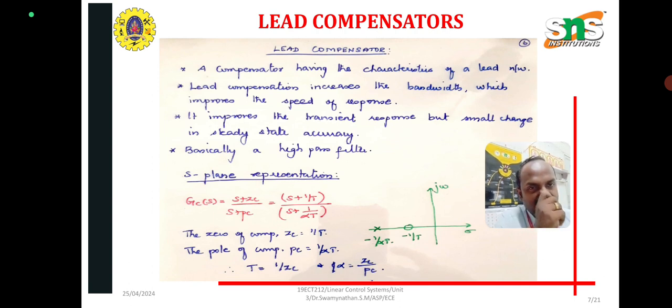So the zero of compensation ZC is equal to 1 by T, and the pole of compensation PC is equal to 1 by alpha T. So T is equal to 1 by ZC, and alpha is equal to ZC by PC. So look at the zeros and poles for the lead compensator.